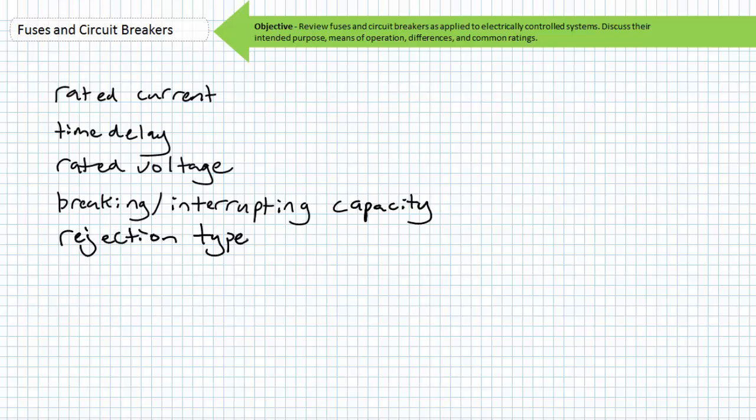When you need to protect your circuit against a draw in excess of 5 amps, you specify a fuse with a current rating of 5 amps. Follow NEC guidelines for determining the recommended fuse size. Time delay. Depending upon the composition of the metal alloy element, this opening action could happen quickly in the case of a fast blow fuse, or take a measurable amount of time to do so for a slow blow fuse.